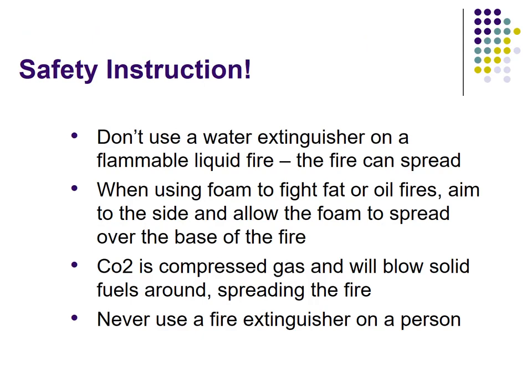Safety instruction. Okay, when you are handling the fire extinguisher, you should take care of your own safety. Here are some instructions that can be helpful for you. Don't use the water extinguisher on a flammable liquid fire. The fire can spread. When using the foam to fight a fat and oil fire, aim to the side and allow the foam to spread over the base of the fire. CO2 is a compressed gas and will blow solid fuel around, spreading the fire. Never use the fire extinguisher on a person.